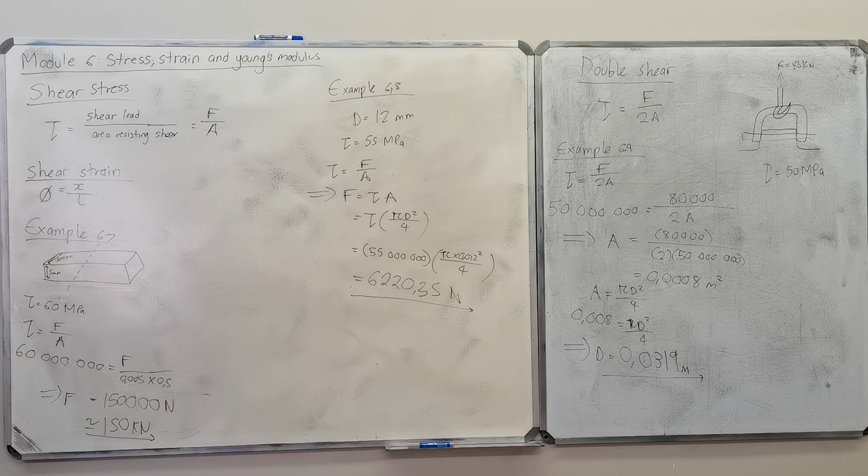It's difficult, eh? So 32 millimeters when you convert it. If we give you something like a clevis bolt, where one side is thicker and the other side a bit thinner because it's threaded, then you won't say 2 times the area because it's not constant area. It will be the force divided by the area of one side plus the area of the other side.